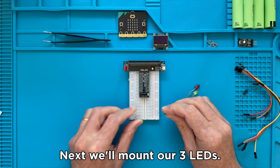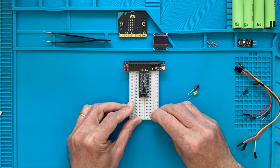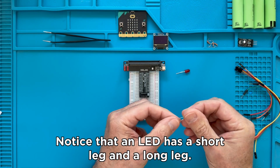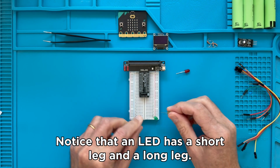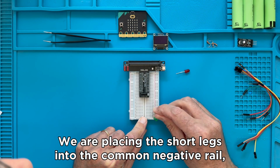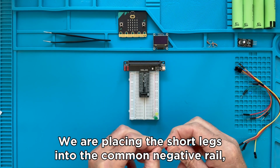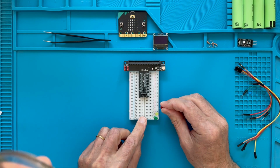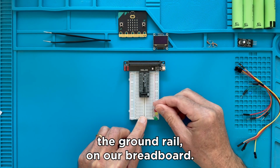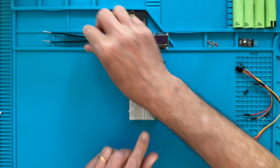Next, we'll mount our 3 LEDs, and notice that an LED has a short leg and a long leg. We are placing the short legs into the common negative rail, which is also sometimes referred to as the ground rail on our breadboard.